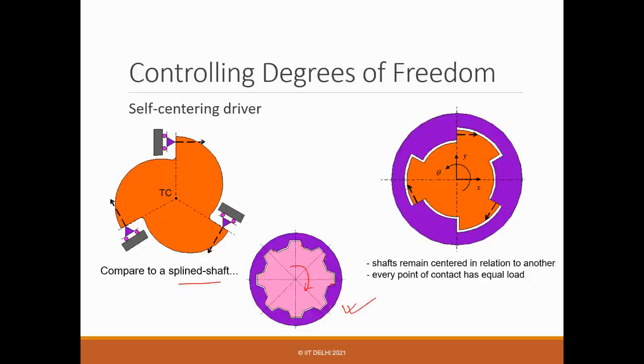Yeah, because when we design, we say that, okay, all of them are transferring, right? But this is not true. This is just a hypothesis. If it's very squeezy and has very low stiffness, okay, it will just move and then start pressing. But if it's a hard material, it might be making contact in just one or two places only, right? Of course, you talk about averaging, and you say, okay, after wear and tear, it will make contact with another one. So those are the other criteria.